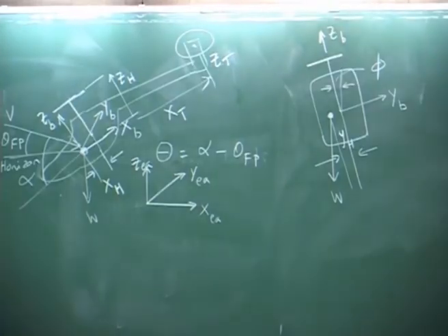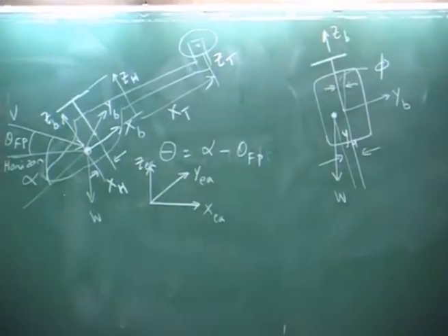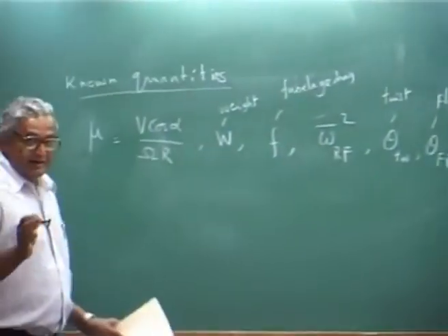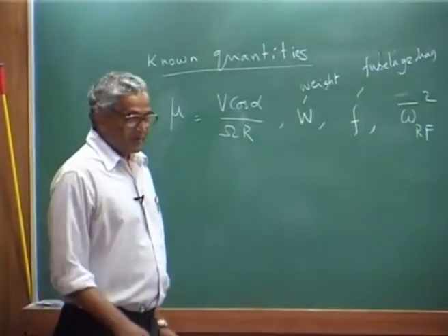Now you know that because these are helicopter maneuvering anything, these rotations are not small angles, okay. So you have to follow Euler angle transformation, okay. The Euler angle transformation I will write between this, you find out the sequence of rotation.